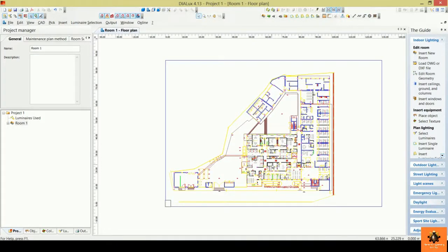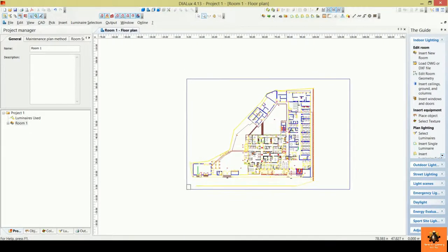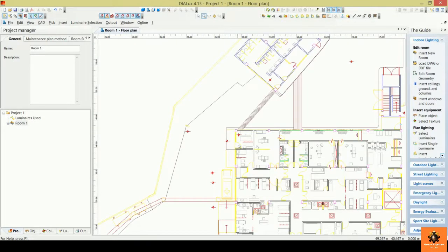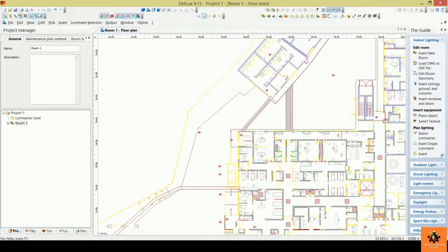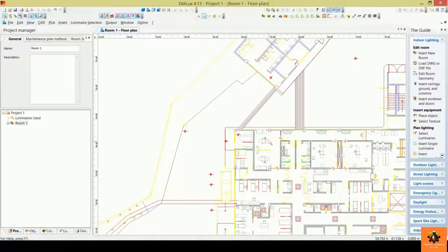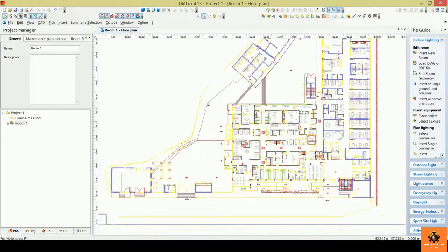And also we have another method to zoom in or zoom out in the program, and this is by pressing on this magnifier. Here you can see we have the magnifier tab on the DiaLUX software. If I press on it you can see the mode is changed to the magnifier, and in that case if I need to zoom in I easily press a left click, and while keeping the left click pressed I move the mouse to the right or left. As you see, if I move to the left, I'm zooming out, and if I move to the right, I'm zooming in. So when moving to the right and left while I'm pressing a left click, I can zoom in or zoom out, and also by using the scroll of the mouse. Anyway, this is how you can zoom in or zoom out in the program.